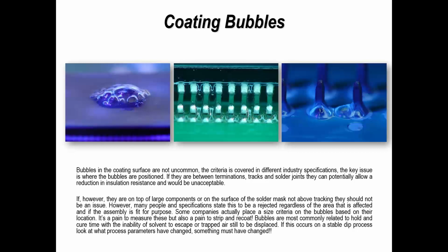Not saying it doesn't happen, but I haven't seen it or been asked about it. So we may well have got away from the materials, the processing of tin plated finishes that caused that in the first place. But again, there are still a lot of companies that are concerned and use conformal coating as a mitigator against tin whiskers.